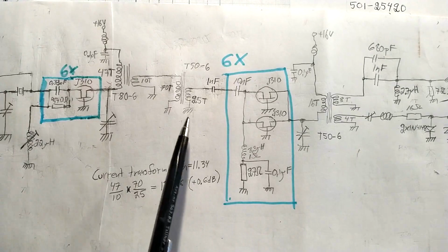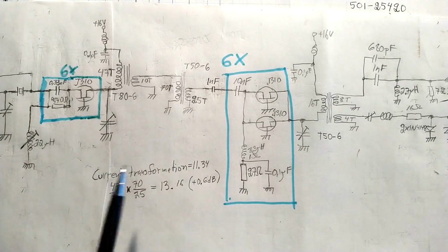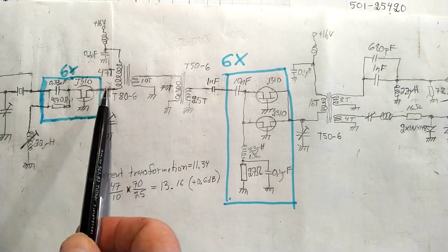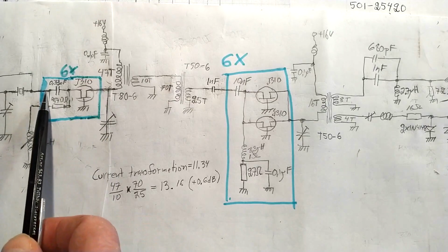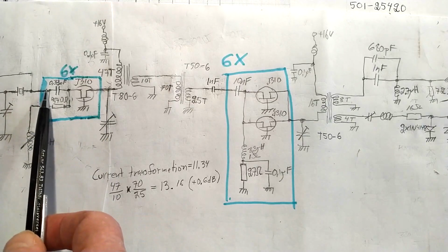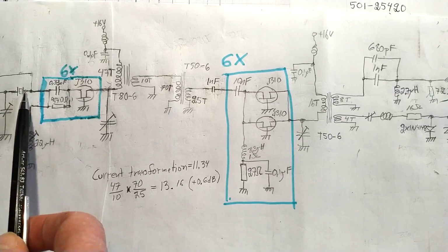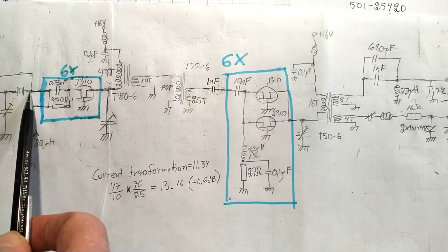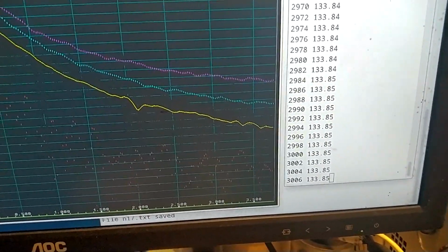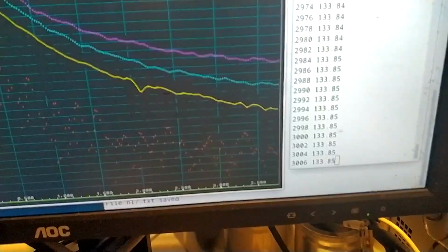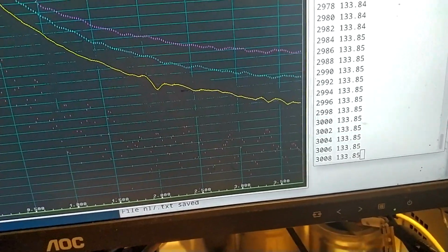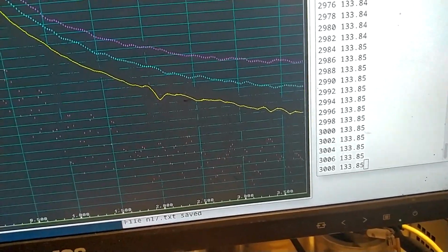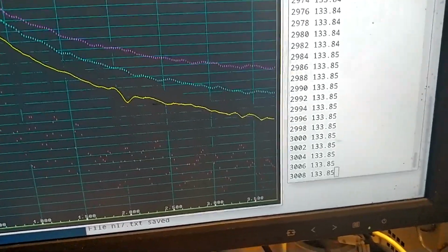A larger transformation ratio here means that the impedance that loads the drain becomes a little higher, which means that the crystal will see a little bit higher impedance on the sources, and that should degrade the loaded Q of the crystal slightly. I see no degradation of the noise close to the carrier, and this is the average from 2.2 up to 3.7 Hz, and it's the same as before.